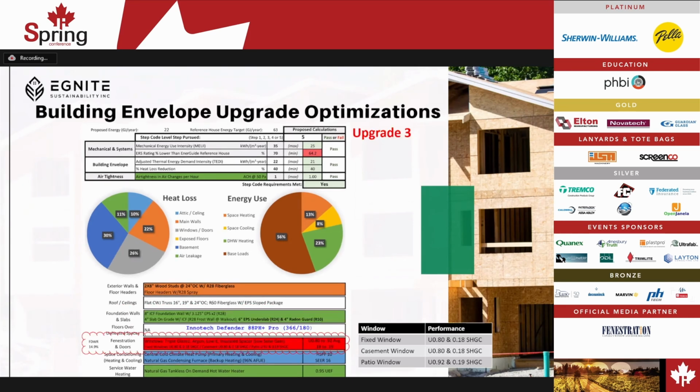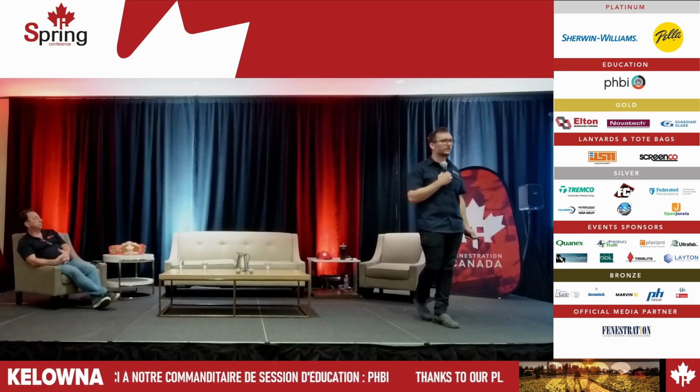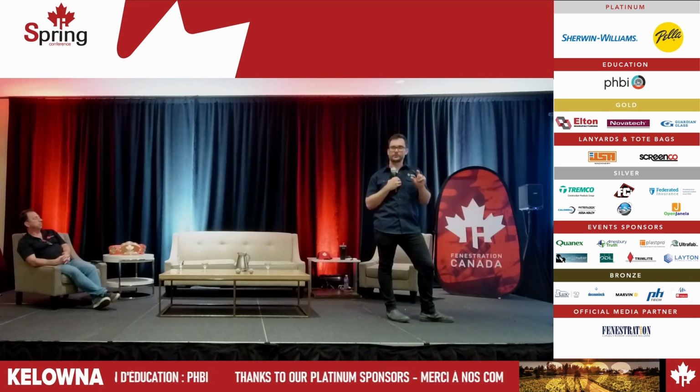Upgrade option number 3, we ended up doing their conventional above grade wall assemblies, their conventional ICF, with the underslab insulation. We were able to quote a very high performing triple glaze window package. It was a Passive House equivalent window package around a 0.8. And they were able to hit the Step 5 metrics by going with a very high performing triple glaze window